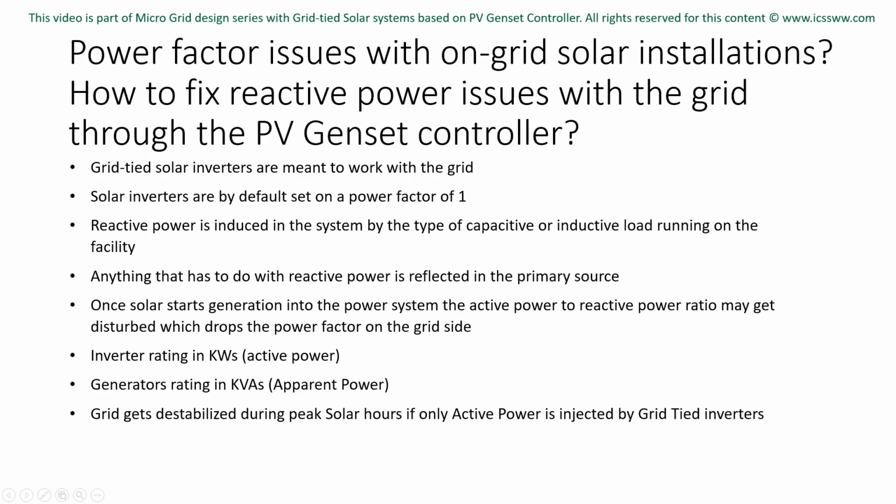For a region with net metering allowed by the grid, if the distributed domestic, commercial and industrial installations will only be including active power to the grid, the power factor, which you can also refer to as quality of electricity, gets disturbed, especially in peak hours. Loss of quality or poor power factor incurs losses to the grid company because of energy wastage, and the balance of power is also impacted.